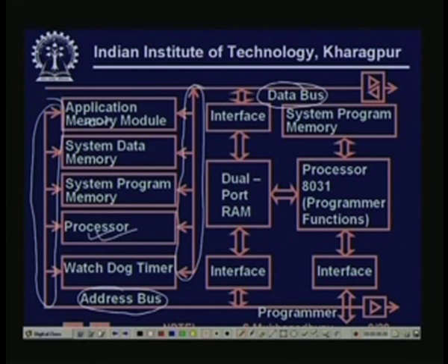You have application memory where the computational tasks run. Even for running tasks, for managing the resources of the PLC, you need some programs which are typically called systems programs. So for that you need systems program memory, you need systems data memory.